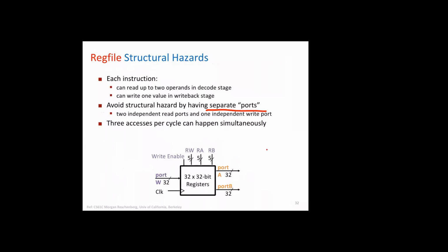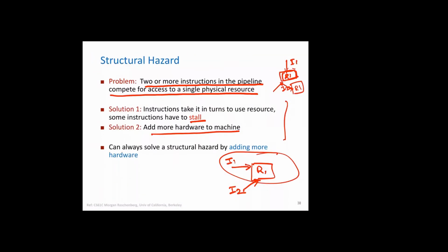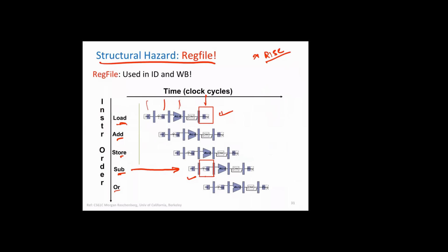That's what is shown here. For example, if you take the same example here, we can avoid this by this design. Just one part was skipped: this concept where register reading and writing can happen together, in the same cycle, is called double pumping.